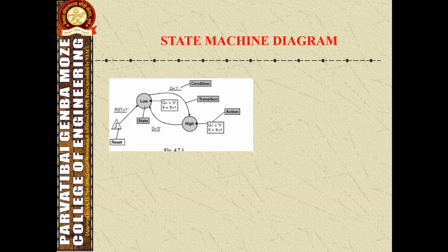Next is transition priorities. If two or more transitions coming out of the same state simultaneously evaluate to true, they should have different transition priorities assigned. By default, all the transitions on a state diagram have priority 0, which is the highest possible. Priority value can range from 0 to 9. A transition with a lower priority value takes precedence over a transition with a higher priority value.